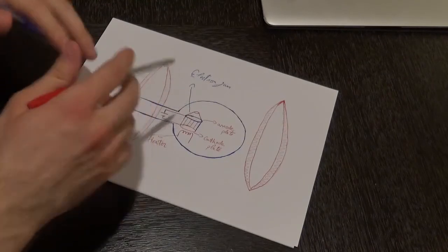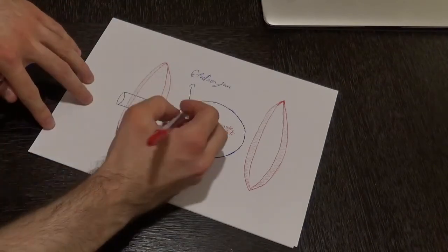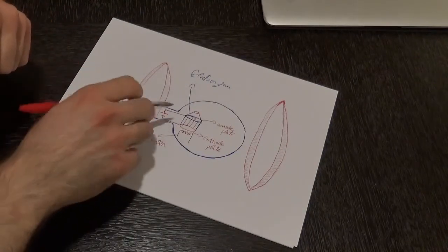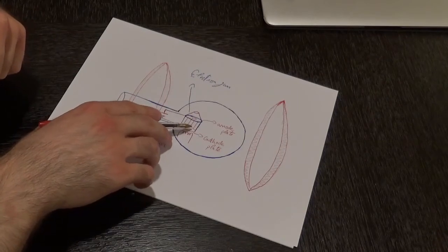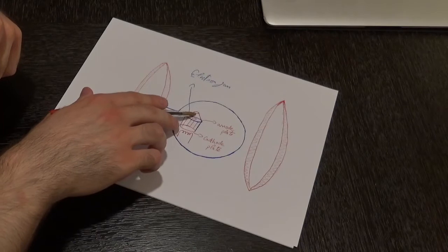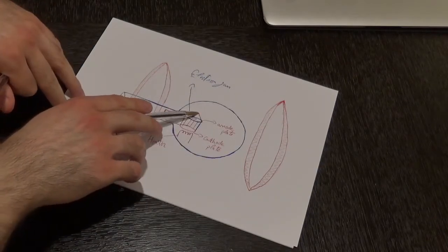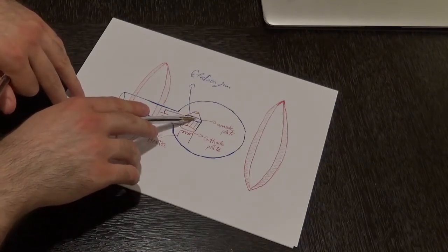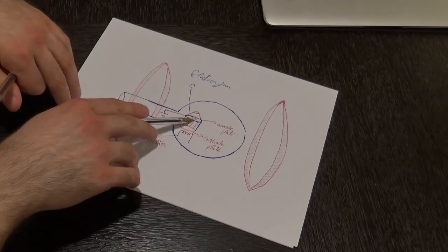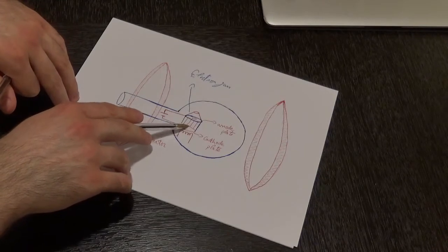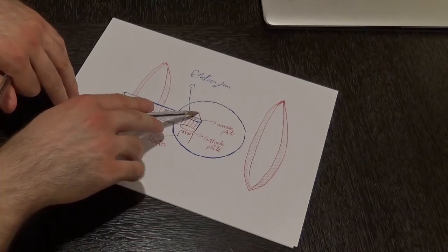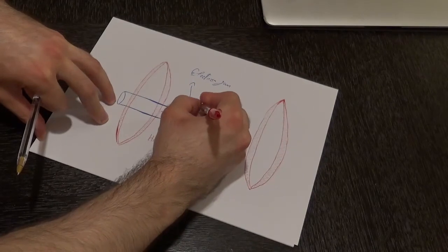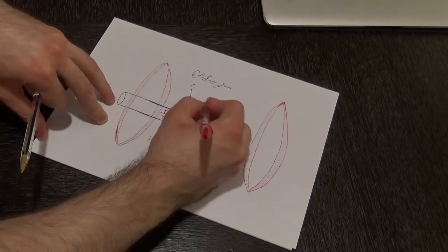Now the anode is going to be equipped with a special feature. In the middle of the anode we are going to have a small hole. We are piercing the anode in the middle in order to allow a fraction of the electrons generated by the cathode to pass through that hole and then enter into the bulb region. So at the apex of that electron gun we have a small opening, and right beneath that we have another opening pierced through the anode plate. Therefore, a small fraction of the electrons pass through that opening, then through the apex of the electron gun, and enter into that bulb region. For example, let's consider that we have the following fraction of the electrons entering into the bulb at a certain velocity v.